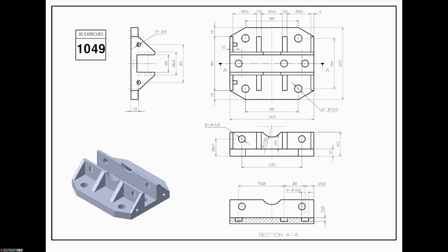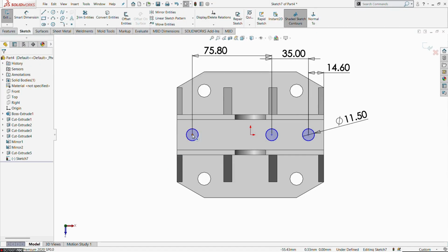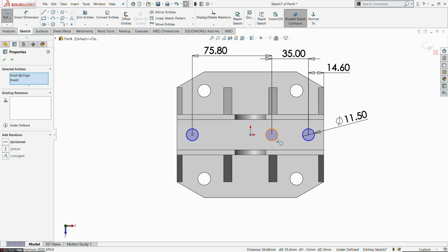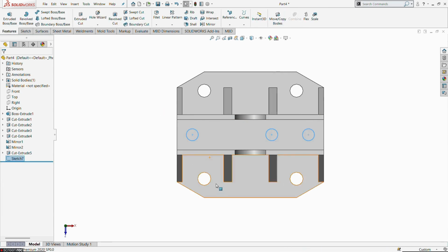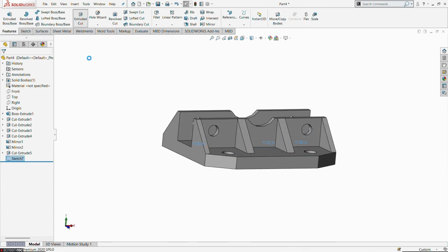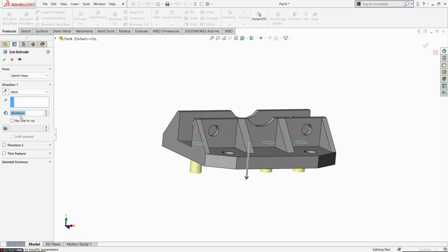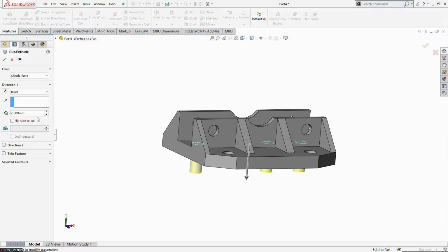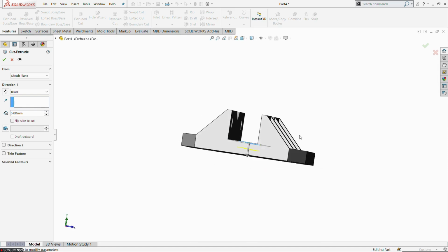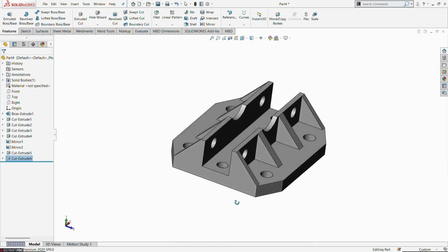Afterwards, select each of the center points to fix them linear. So select the first one, the origin point, the second one and the third one. Then use the horizontal constraint. Then exit the sketch now. Afterwards, if you want to create a proper pocket on the right section, it cannot cut the entire body. We need a distance value, that is 5.8 mm. So mention 5.8 mm to make a cut under this distance.